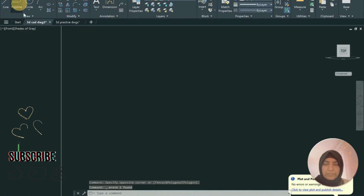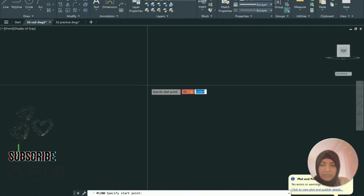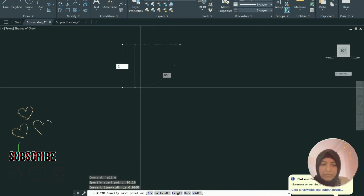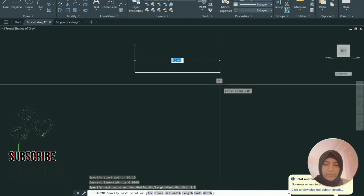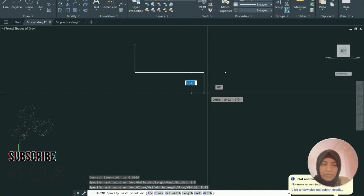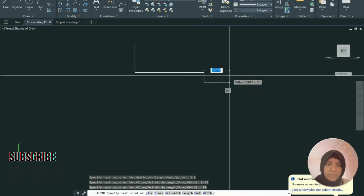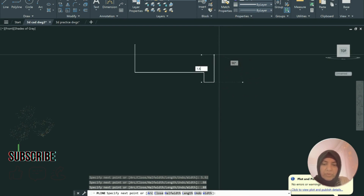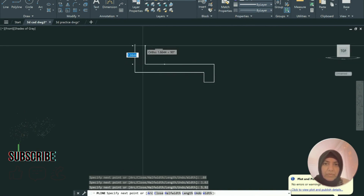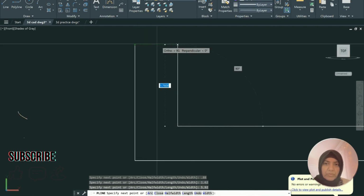Start with polyline at 10,10 and go down 2.5, go right 5.92, go down 0.88, go right 0.88, go up 1.62, go left 5.92, and go up to this point.